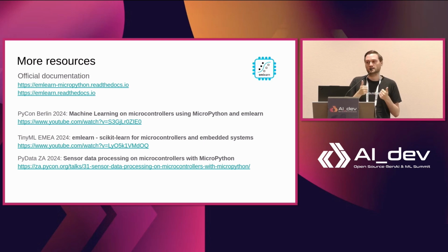But object detection is not on the upper edge. Microcontrollers, some of them are now pushing 600 megahertz clock speeds, dual core, and you can even have SDRAM on it, so like 100 megabytes of RAM. So yeah, if you go with the higher end, you can do quite a lot of computer vision. And there are projects like OpenMV, which really focuses on that exact area, and they provide tools there.